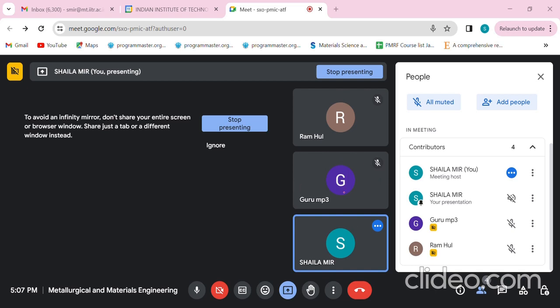Then it says that it is because of a dislocation. That is also not possible, because we are talking about a mismatch in the crystalline orientation of a grain. We are not talking about an atomic arrangement, right? Dislocation is a mismatch of the lattice, a mismatch of the atomic arrangement, not of a grain. So this is also not the right option. So the right option is grain boundary.